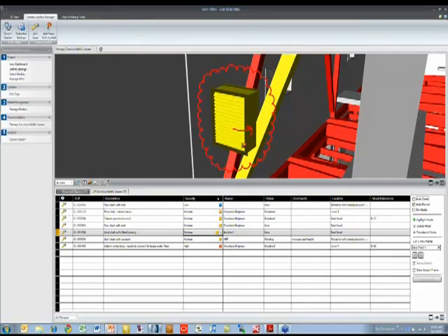So this one here, we can see that we have a vent clashing with a steel brace, and we need to make sure that the architect changes something here. Maybe we can move the vent, but potentially it might affect something inside the building as well. So once we have this information, and we are pleased to say that we have caught constructability issues and we have rejected the detected clashes that aren't potentially clashes, then we can start to create reports on this information.